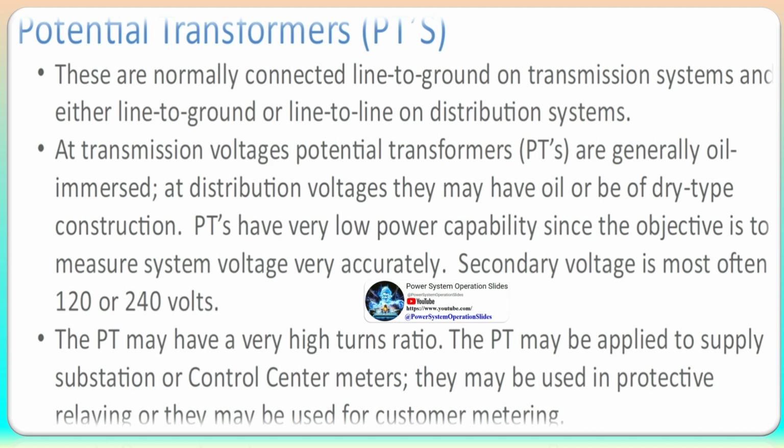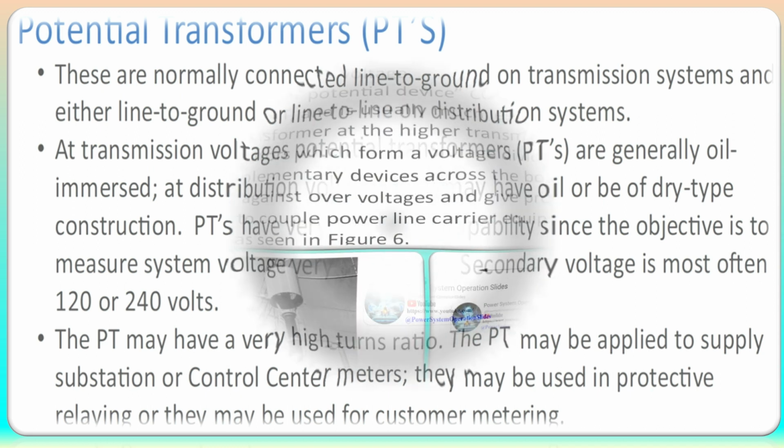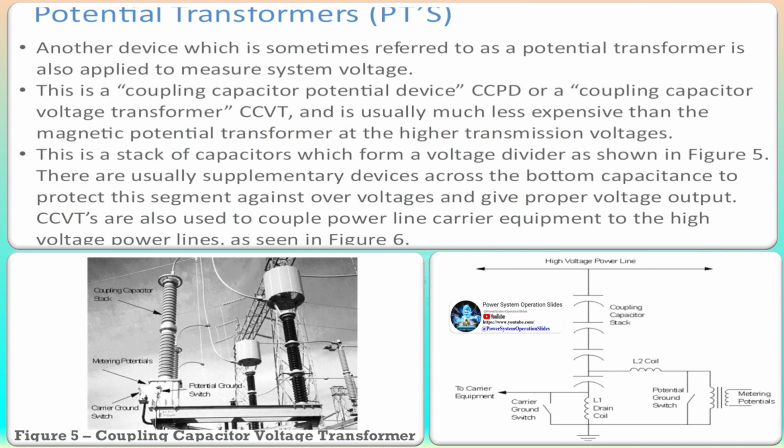Ground banks, or grounding banks, are used in power systems to create a reference point for the system voltage, to facilitate the flow of fault current, and to reduce the effects of electrical noise in the system. Ground banks are also used to provide a path for current to flow from the system to the ground, enhancing safety and preventing damage to equipment. Effective grounding can be achieved with a grounding transformer.